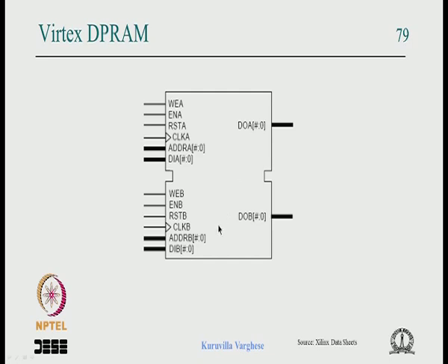So in principle you can have multiple ports, you have the same location, use another mux with the second set of address lines to read another location. Similarly, as you are writing to one location, you can have an address decoder clocking yet another location. So that is how the dual port RAMs are built.